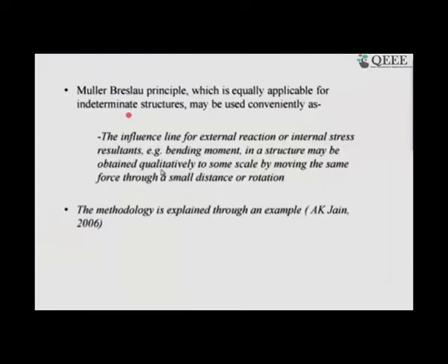Rather, let us examine whether there is a somewhat convenient way using the Muller-Breslau principle. The Muller-Breslau principle, which is equally applicable for indeterminate structures, may be used conveniently to determine the influence line diagrams for indeterminate structures. The influence line for an external reaction or an internal stress resultant, as for example bending moment in a structure, may be obtained qualitatively to some scale by moving the same force through a small distance or rotation.